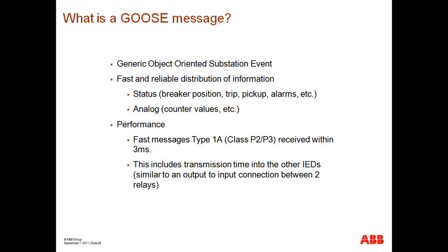One of the questions that I often get is, what's the performance? Well, you have fast messages, which are based on 61850-5, type 1A for class P2 and P3, which these messages should be received within 3 milliseconds. When looking at the performance specifications,